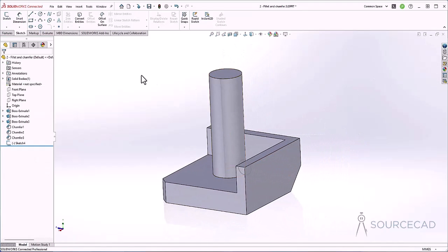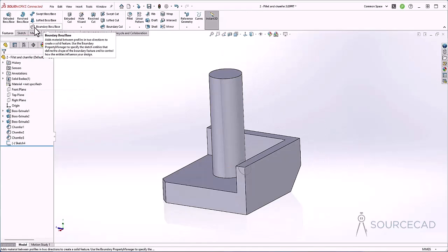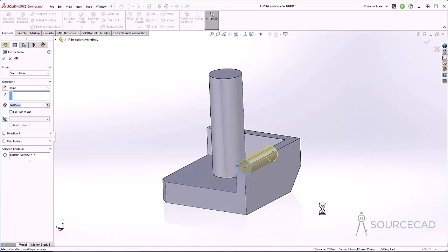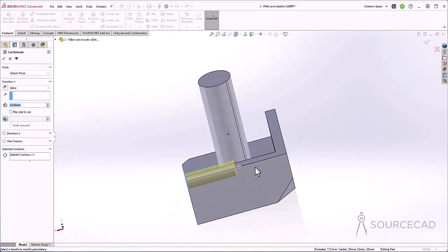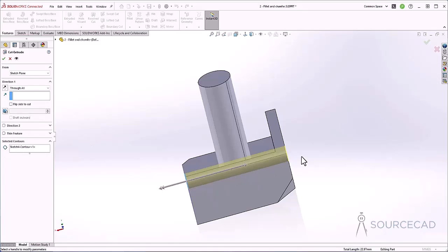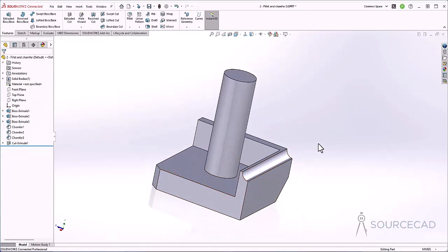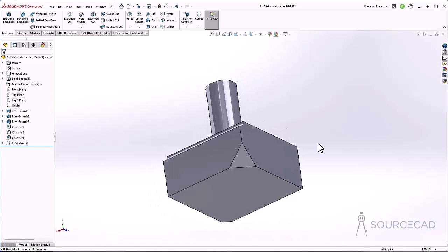And now we can use this circle to cut this 3D object. Well, let's try that. So I'll go to feature and I'll select extruded cut feature. Now select the sketch, and there we have the cut feature. Now you can specify the blind distance, or you can use the methods that we used previously. In this case, maybe let's select through all, and that's going to make this complete cut. Click OK. And here we are, we've got this cut feature. So instead of making things, it's going to remove things from your drawing. In a similar way, you can use this to add different kind of cut features.